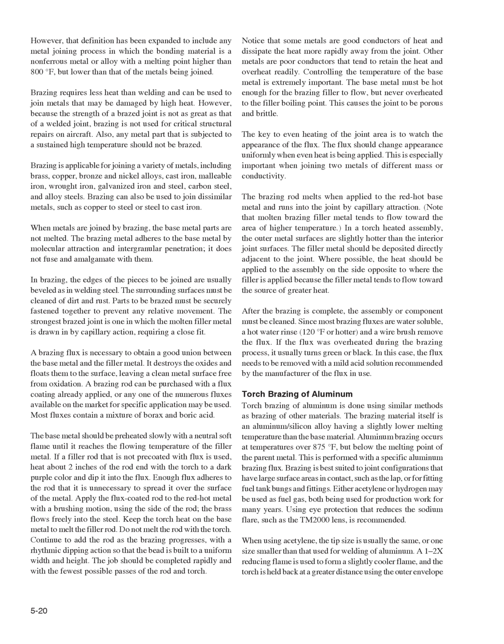Notice that some metals are good conductors of heat and dissipate the heat more rapidly away from the joint. Other metals are poor conductors that tend to retain the heat and overheat readily. Controlling the temperature of the base metal is extremely important. The base metal must be hot enough for the brazing filler to flow, but never overheated to the filler boiling point. This causes the joint to be porous and brittle.